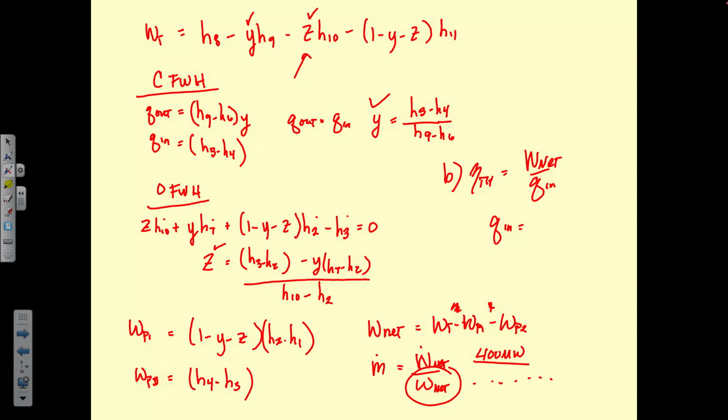Yep. So we have an H8 minus H5, which is the Q from the boiler. And then the Q from the closed feed water heater is, no, that's not a Q in because that's a regenerator. So we don't have to worry about that one. So Q in is just the Q in from the outside, which is the boiler. If you were to draw a system boundary around this entire thing, that's the only Q you would see.